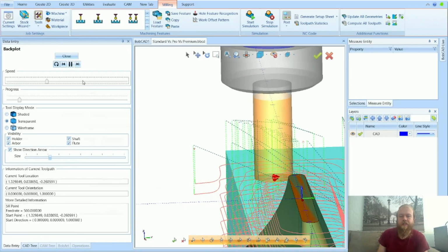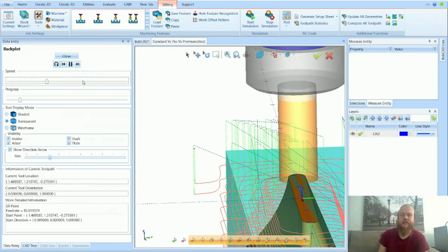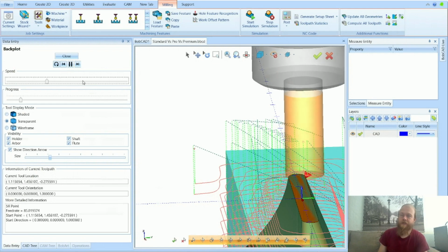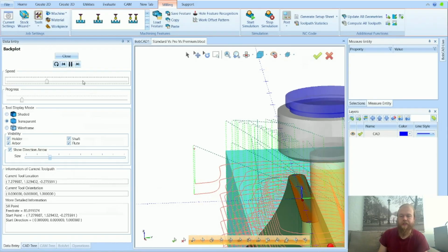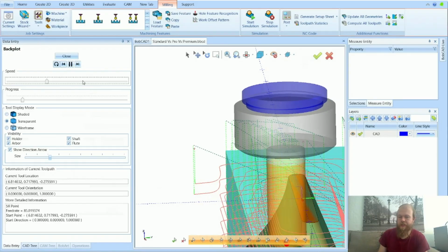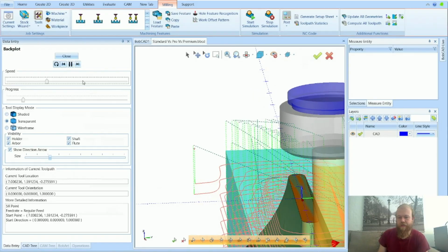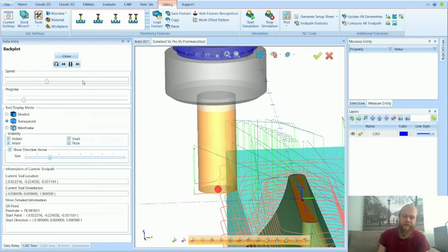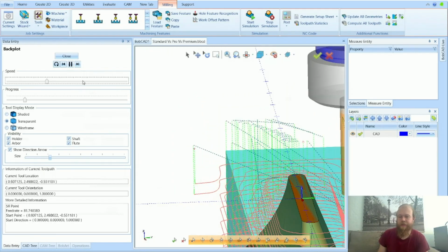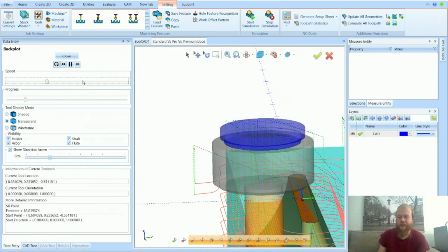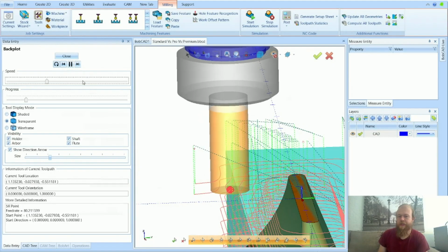We'll be getting into some of the 3-axis standard versus 3-axis Pro finish operations. And then we'll get into the premium toolpaths, which are finish operations only. There's not really any roughing operations there. And the premium is a surface-based toolpath. So you're selecting specific surfaces, and it will create toolpath right along the specific geometry.